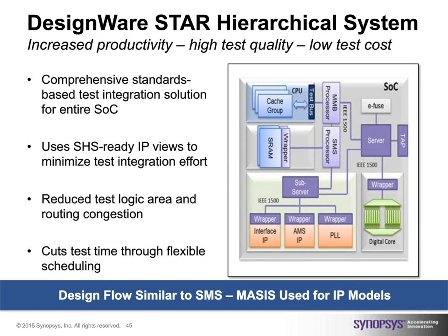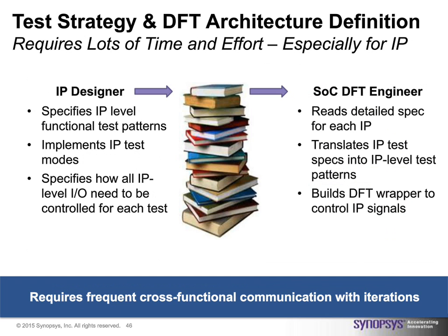This pink infrastructure complements the SMS infrastructure that we saw earlier. So besides SMS, there is a complementary piece here called the STAR Hierarchical System that allows us to test, debug, as well as fix those mixed signal IPs beyond memories. Thinking beyond memories is important in those chips. With that, we take the test information from the small set of IPs or large set of IPs, which patterns, which IOs need to be taken care of, which test modes, and so on, capturing it into a model that the STAR Hierarchical System automatically recognizes, and accordingly builds the SoC solution on it. It's a hierarchical solution, as you would expect.